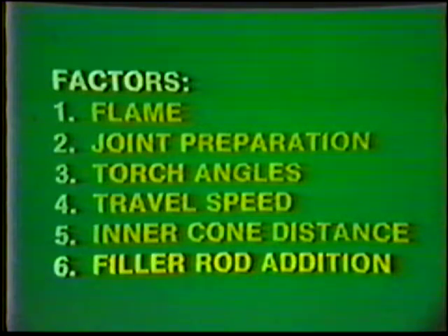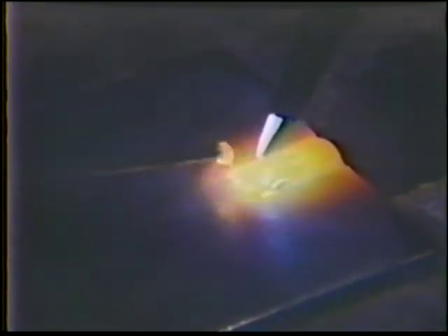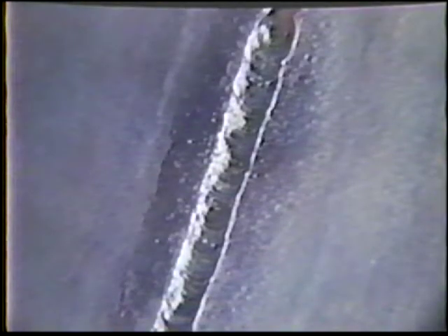Filler metal must be added in the portion of the puddle that is hot enough to melt it. Touching the rod to colder areas will result in its sticking to the work. Poor appearance is the usual result. Not adding enough filler metal may result in undercut or underfill of joints. Too much filler metal is wasteful and produces a weld of poor appearance with excessive reinforcement.